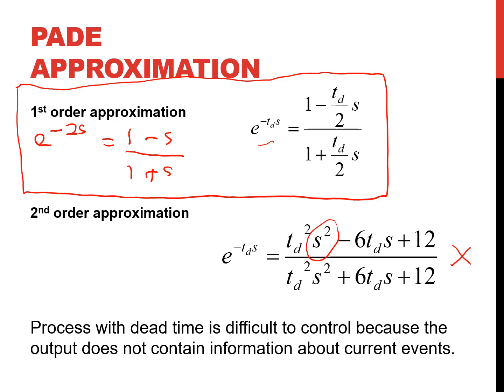Usually, we don't want the time delay as the exponent, because first, it's very difficult to do the inverse Laplace, leading to the difficulty to solve the problem. And if we try to do the control on the time delay, then it becomes harder to maintain the operation at its set point, because the process becomes unpredictable.